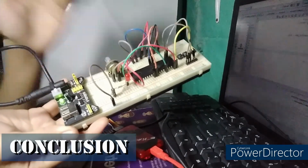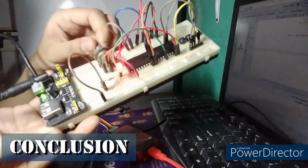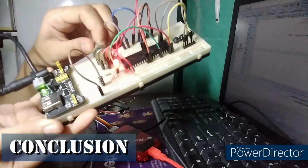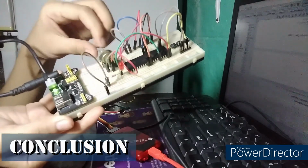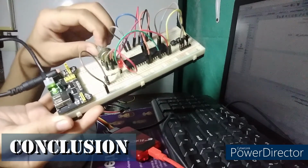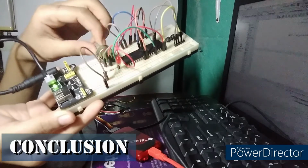So this allows us to convert an analog signal from this potentiometer to a digital signal that can be processed by our microcontroller, giving us a digital input that will be conveyed through digital output through our LED. That's one of the applications of our analog to digital converters, which is really essential in programming and in setting our electronic components and circuit boards.